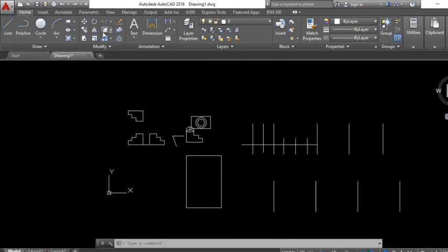This thing will be, since it's a polyline, or let's say a joined line, a rectangle that you draw, and suppose it's a polyline. So what are you going to do? You see, it's a polyline, but if I put the pointer there, it's being selected individually. The reason is fillet deals with lines and other lines, corners. That's why it's selecting individually. Meaning I've selected this line and this line. So what is the angle between this line and that line? It will fillet that angle.